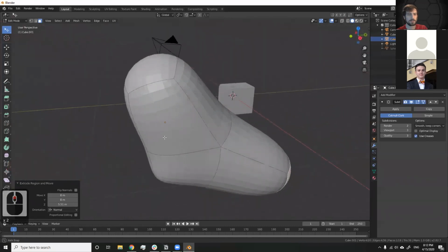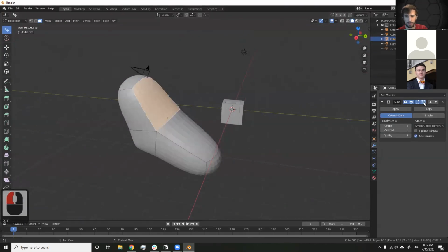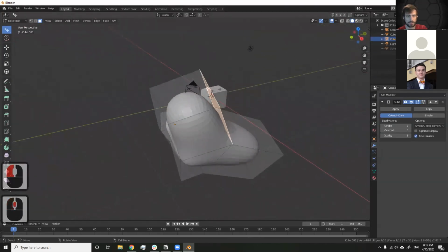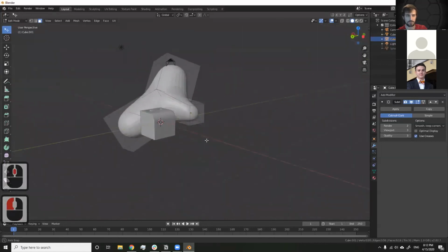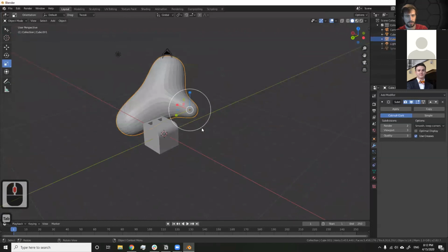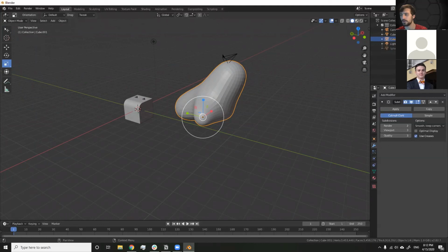It just basically depends on your preference which one you like better. Some people like selecting the faces directly on your model. Some people like not having that visible and like being able to see the hard edges on the outside. Basically a personal preference. But yeah, you always have to apply the modifier if you want to make it a permanent change onto your mesh. Any questions about modifiers and editing before we go on to the next step?